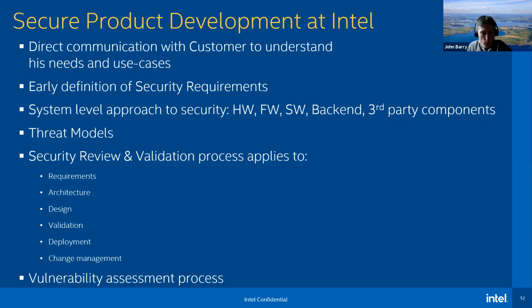One of the pitfalls people can fall into is that a mitigation is put in place, but then they create a debug mode to bypass it for testing, and that bypass mode can be exploited if that debug test mechanism isn't enabled in a secure fashion. So it's not just the architectural mitigations, but the detail of how those mitigations are implemented that is really important.